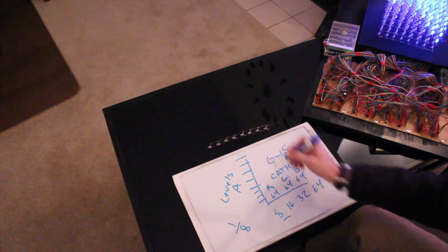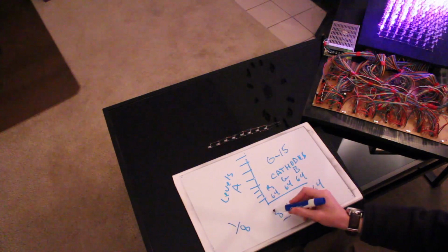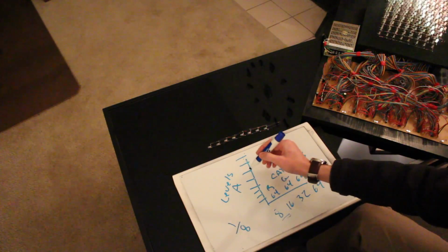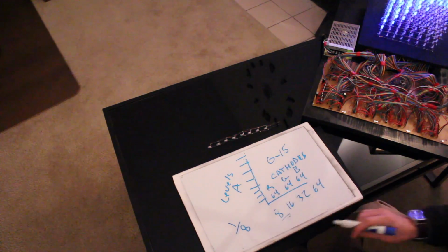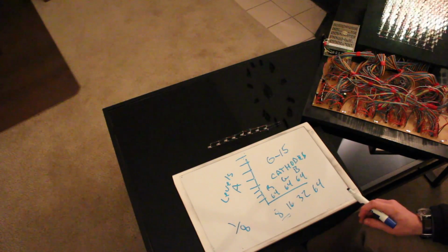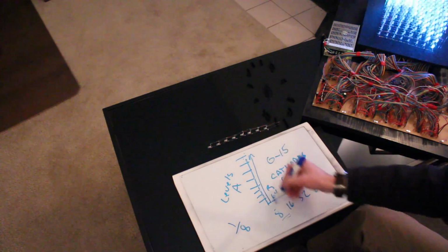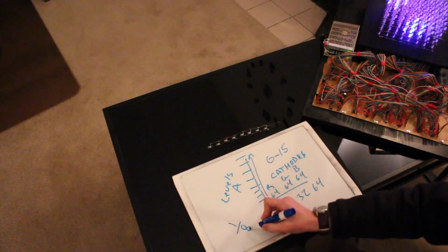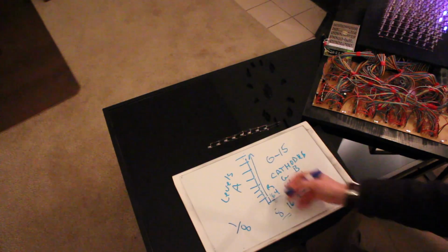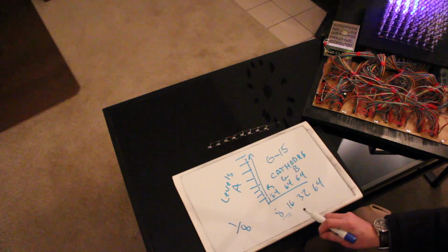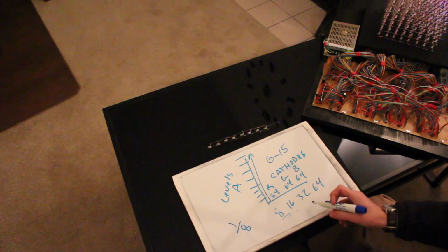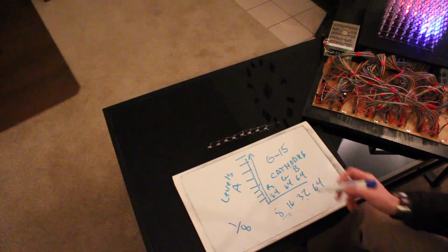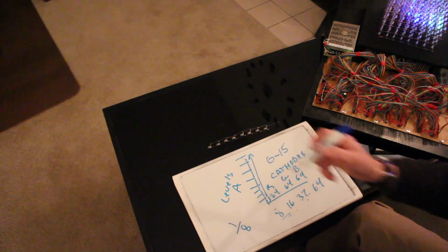So if you wrote a 1 to it, you would be in this column here, so it would be on here for an 8 count, just so every single row has a chance to turn it on at least one time. Okay, because it takes me 8 clocks to get all the way up. So if I did write a 1 to one of them, it would only be on for 1 out of the 8 times anyways. And then it jumps right over to the 16, counts all its way up, which would be 2 of the 8s, and then to the 32, which would be 4 of the 8s.